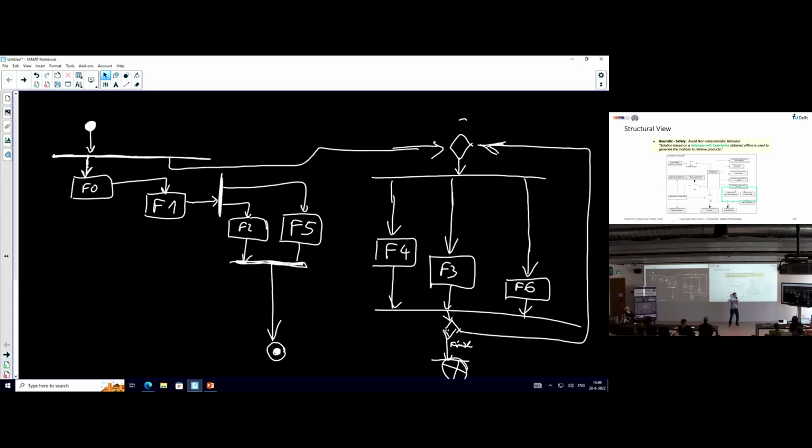So to approach one of the stacks of products, that's always the same trajectory. If we are certain that there will be no obstacles in that part of the environment, we can have pre-computed trajectories. So we avoid online planning and avoid non-deterministic behavior. In this case, and in many cases, we use a trajectory database. We don't plan the trajectories online. We plan them offline, we check that they are valid, and then we use them. And this is used way more often than you think. Robots are normally executing what they were told beforehand to ensure that nothing unexpected happens.